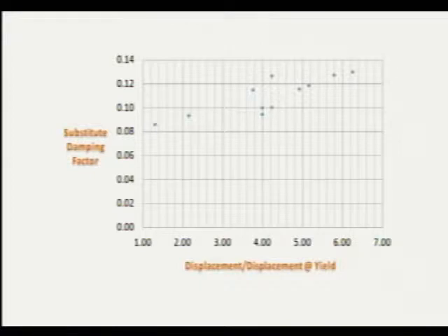It will have about 2% damping if you shake it very little. But if you shake it so that it approaches its yield moment or more, it'll go up to 10% damping. So 10% damping is not such a bad approximation for our buildings.